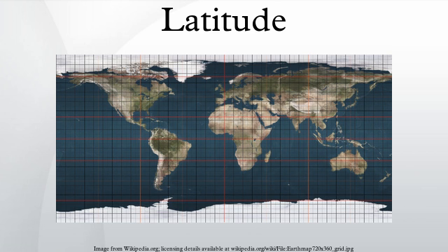Since latitude is defined with respect to an ellipsoid, the position of a given point is different on each ellipsoid. One can't exactly specify the latitude and longitude of a geographical feature without specifying the ellipsoid used. Many maps maintained by national agencies are based on older ellipsoids, so it is necessary to know how the latitude and longitude values are transformed from one ellipsoid to another. GPS handsets include software to carry out datum transformations which link WGS84 to the local reference ellipsoid with its associated grid.